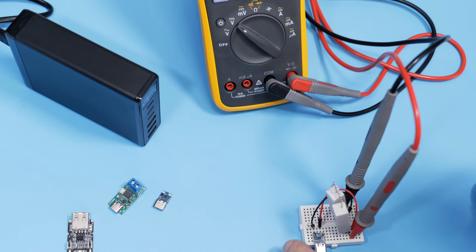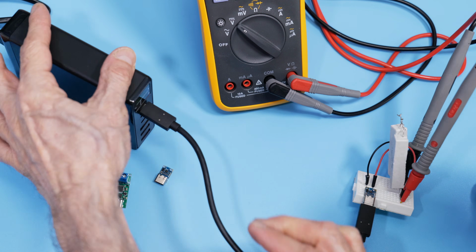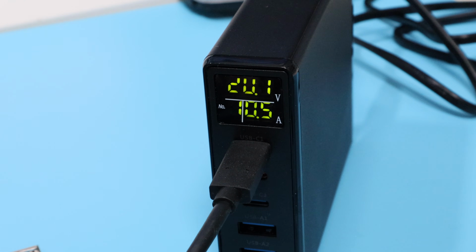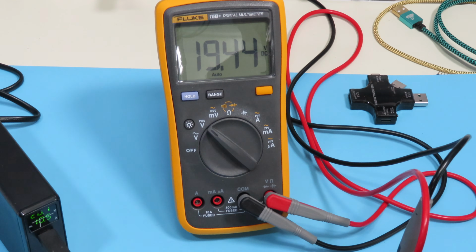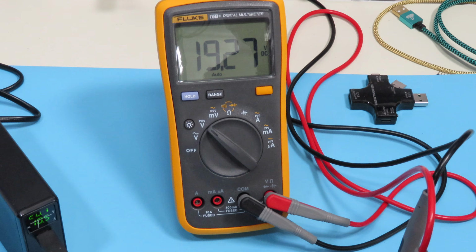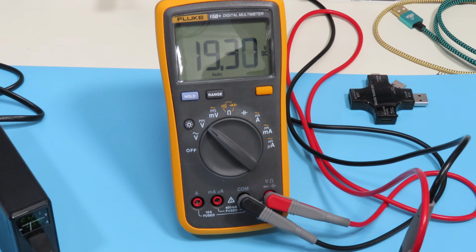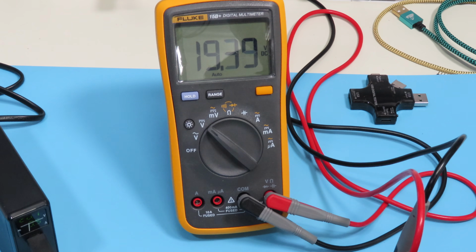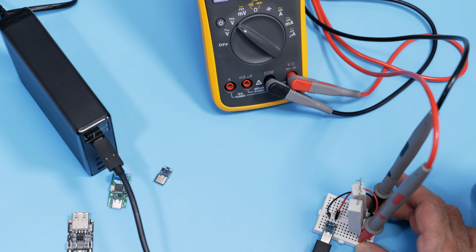And right now, I've got one of those little 20-volt modules on it, so I'm just going to plug that into my USB power supply. And you can see it goes right up to 20 volts. And you can also see that I've got a multimeter on here, and it's measuring the final voltage. You'll also notice some discrepancy between the two voltage measurements, and a lot of that has to do with the voltage that you're losing in the USB cable. They tend to give you more voltage on the supply end to compensate for that. And so this is the test setup we're going to be using.